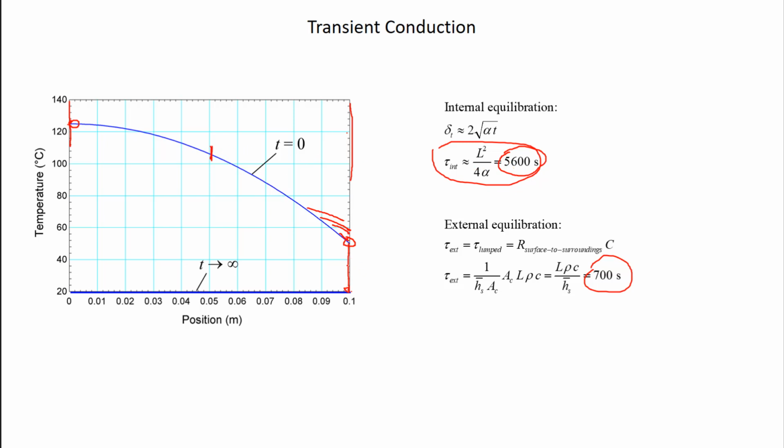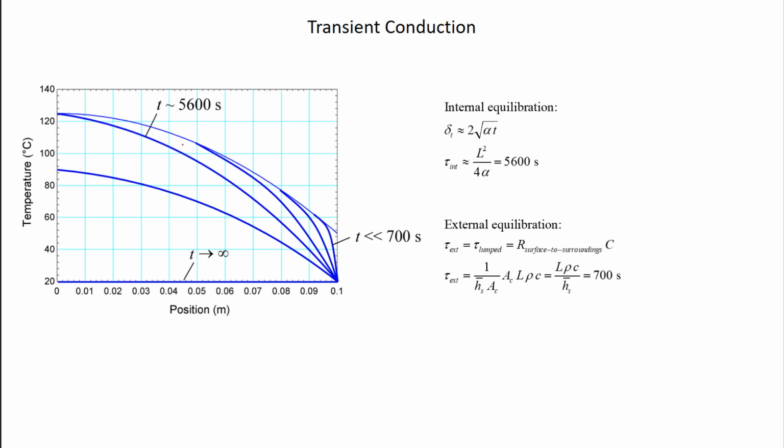So what you're going to get is a thermal wave that moves very slowly through this object, right? Initially, material very close to the surface knows something happened. If I wait a little longer, that thermal wave has moved in a little bit farther, a little bit farther, a little bit farther, and so on, right? So I would get something that kind of looks like this, right? This is temperature as a function of time after about an hour. That's when this thermal wave finally gets to the center, right? And then it takes longer for everything to move down and get to T infinity.